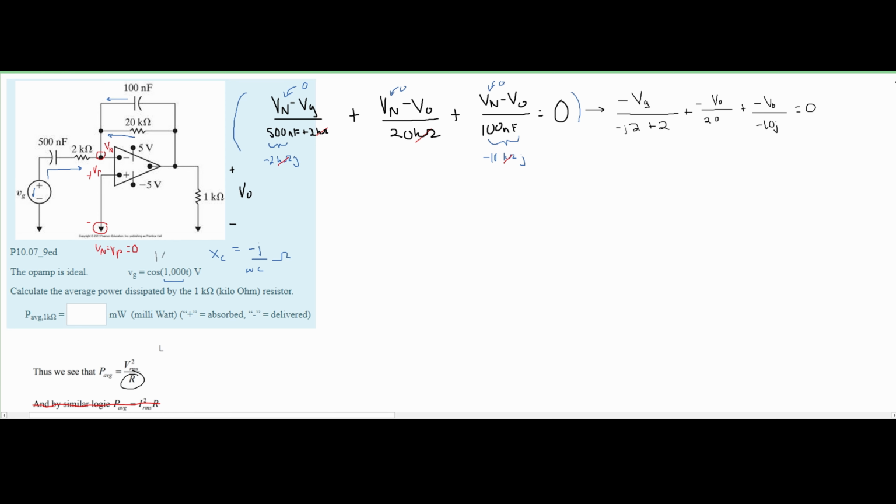What we don't have is our angle. So we're going to set our angle equal to 0. This is the polar equation. If we were to write it in the rectangular form, to convert it, all we would need to do is have our number out front, and then in parentheses have the cosine of our angle, plus j times the sine of our angle. And if we do this, we're going to see that we would just get 1 plus 0j as well. So this is also just 1 for the rectangular form.